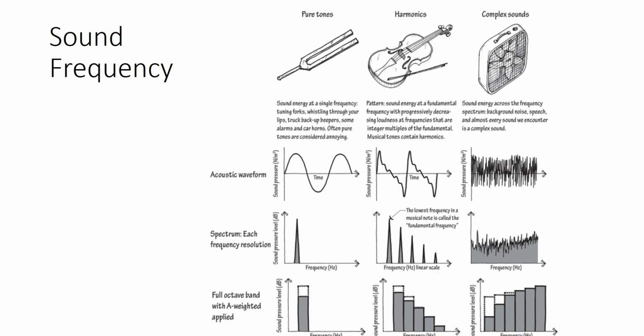And if you have a complex sound source like a ventilator or a fan motor operating, there will be multiple parts generating the sound. It becomes a huge chaotic mix of frequencies, a complex range of frequencies, but there will be some higher frequency levels, with higher sound pressure levels for that particular frequency.